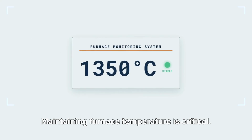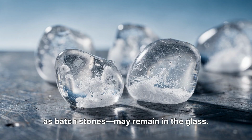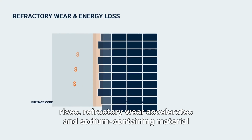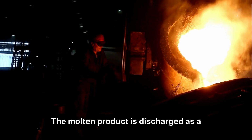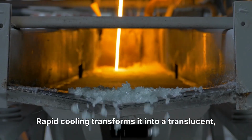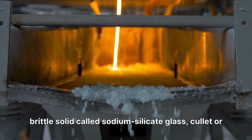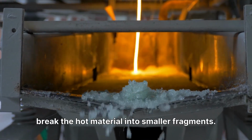Maintaining furnace temperature is critical. If it is too low, unreacted sand, known as batch stones, may remain in the glass. If it is too high, energy consumption rises, refractory wear accelerates, and sodium-containing material may volatilize. The molten product is discharged as a glowing stream onto a cooling conveyor. Rapid cooling transforms it into a translucent, brittle solid called sodium silicate glass, cullet, or lump glass. Water quenching may also be used to break the hot material into smaller fragments.